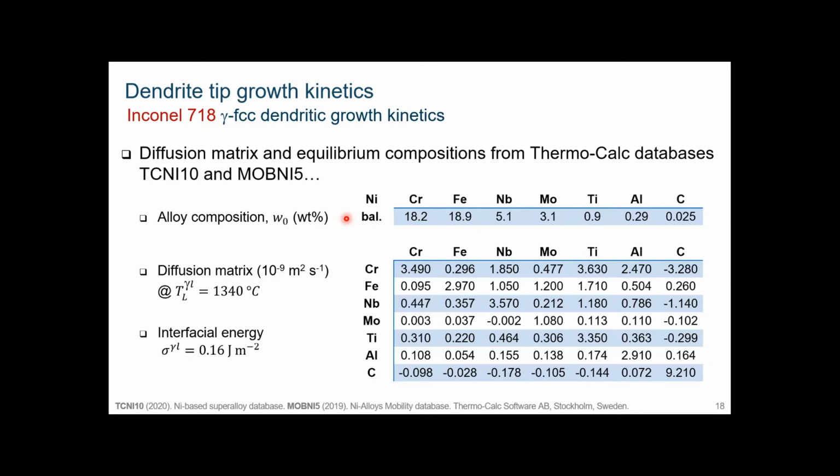You of course compute equilibrium, but with a mobility database you can also extract a diffusion matrix for all solute elements, and this is done at the liquidus temperature of the alloy. One more parameter you need in this model is the interfacial energy, which accounts for the curvature of the interface.